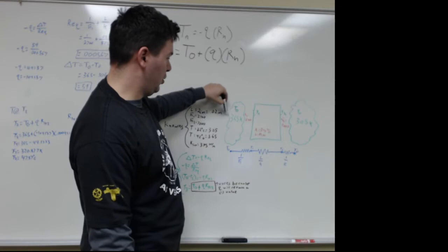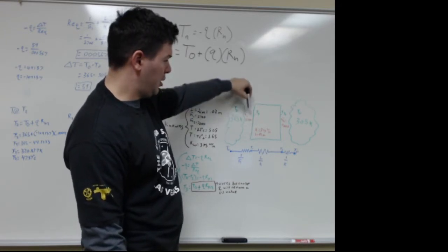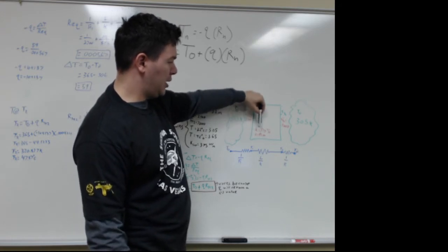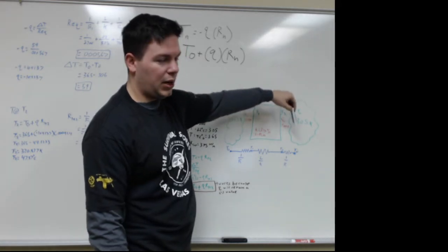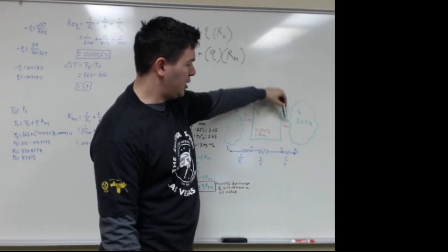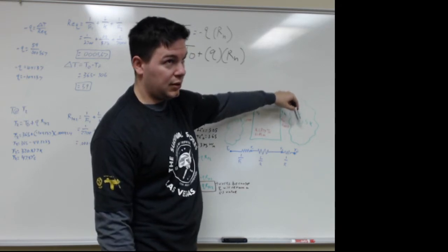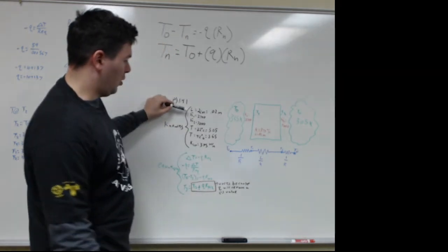We have a temperature initial, converted to Kelvin. We have an h bar for the convection. We have a T1 at the initial boundary of the copper. We have the length and the k factor of the copper given. And we have a temperature 2 at the far boundary of the copper with an h bar given between that surface and the convection of the liquid on the other side with its final temperature. All of that's given in the problem.